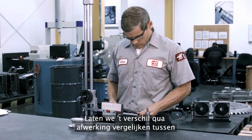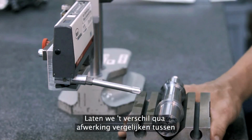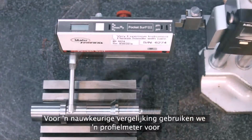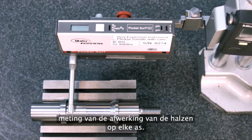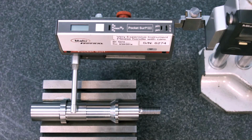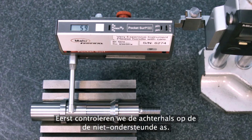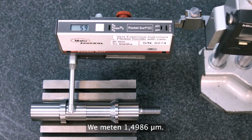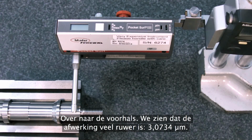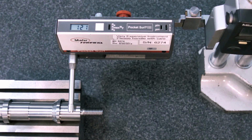Let's see what the actual difference in finish is between the unsupported and supported parts. To make an accurate comparison, we use a surface finish checking instrument to measure both of the finished journals on each shaft. First, we check the rear journal on the unsupported shaft and find a reading of 59 micro-inches. Moving to the front journal, we find a much rougher finish of 121 micro-inches.